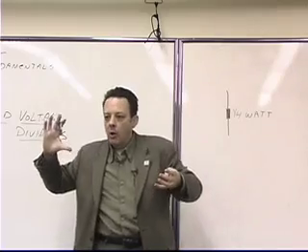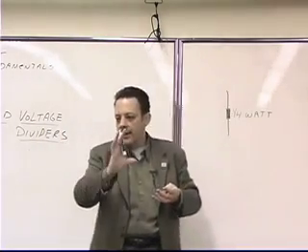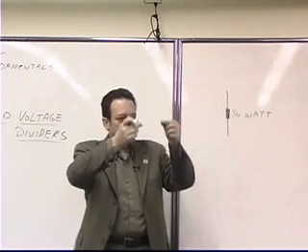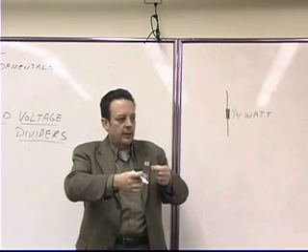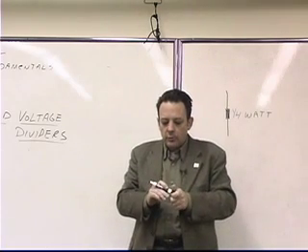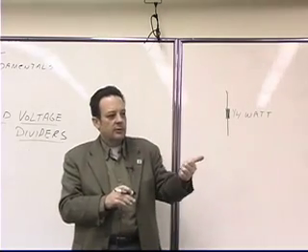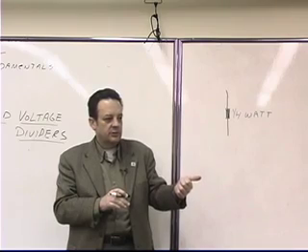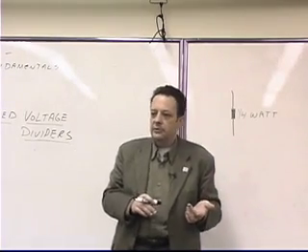We have to blow air across it. Okay, so we have to cool it with a fan. Sometimes we have to design cooling fins into the outer jacket of the resistor. Okay? And these are all things that become pretty much common sense once you have read the material from the textbook or a reference book on resistors, and you've done a couple of experiments with resistors.